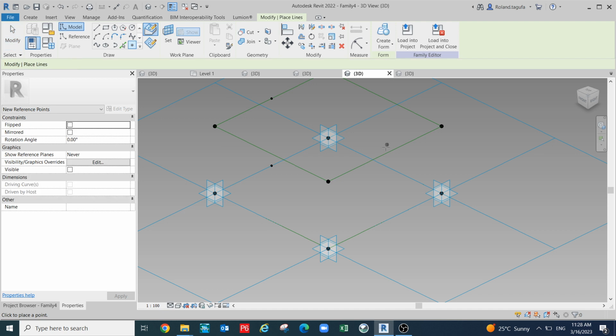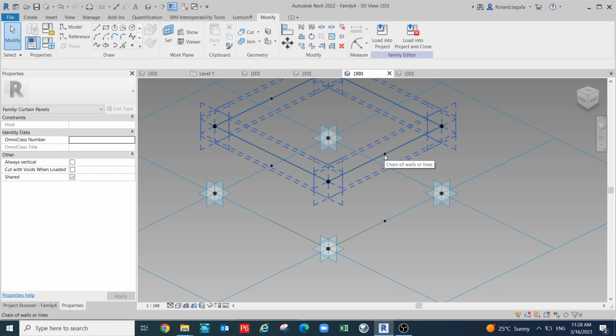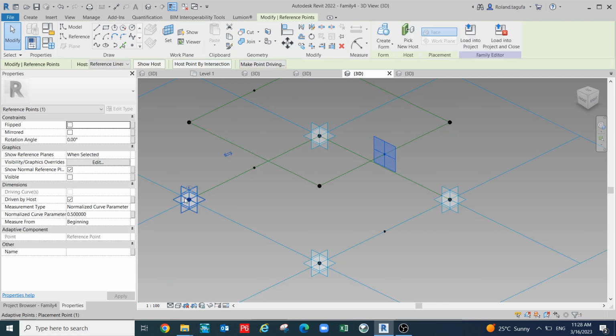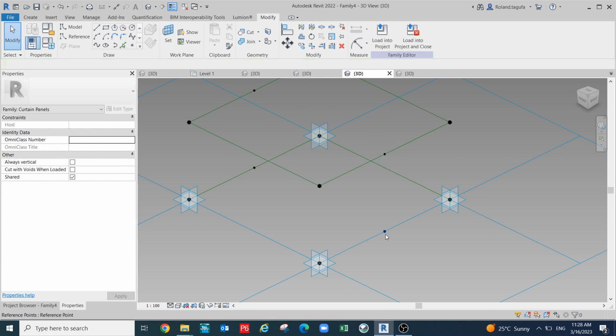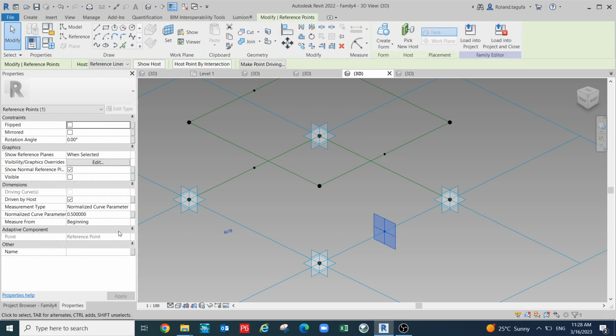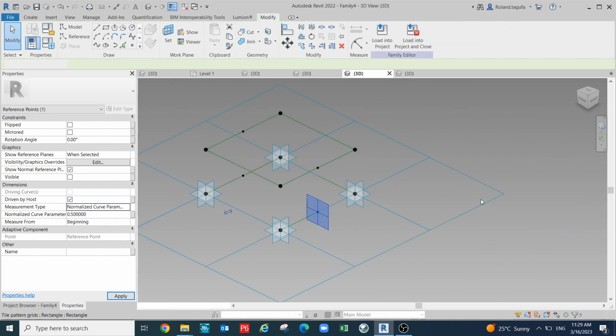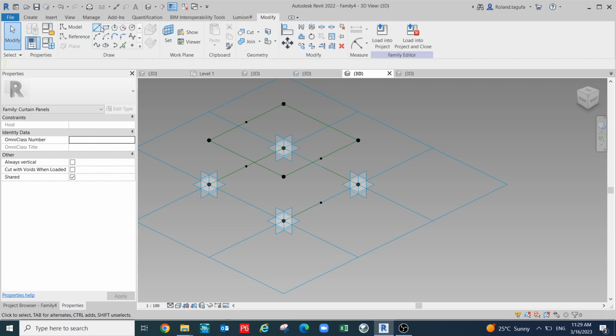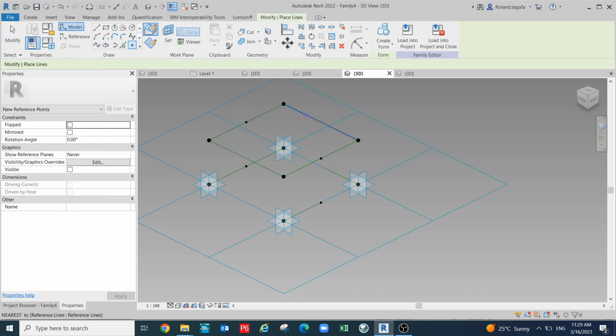I want you to create a point here and a point there. And this point is also beginning 0.5 and beginning 0.5. This is not segmental. You can change the segmental and change segment length, and you change it into length distance. It's like this. And then another point that we need to create is in this point. Create a point here and here.